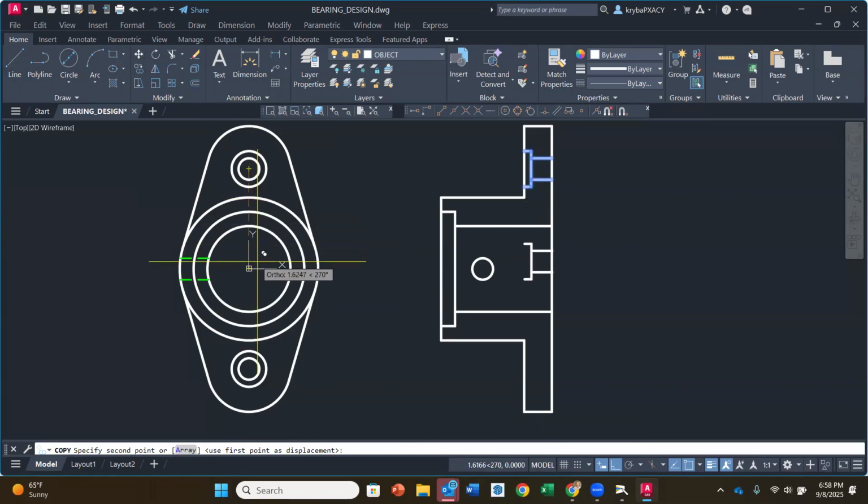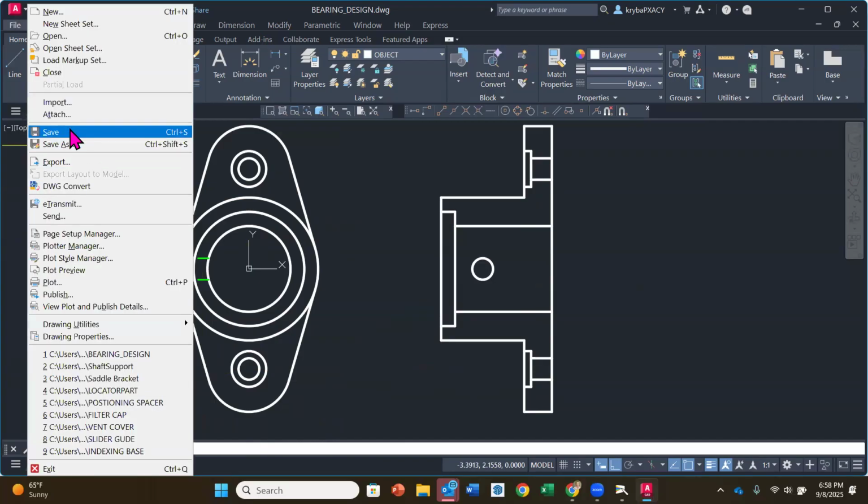I'm going to activate the center of the circles over in the other view. And I'm going to go down and notice it's grabbing a copy. And my second point is going to be the center of the other set of holes. Okay. So, and that went down. Now I can continue making copies, but I'm done. I can either hit escape or enter and I've got that down there. Okay. Just another way. You could mirror it if you wanted to. Oh, you can do a copy as well. All right. Good time to do another save.